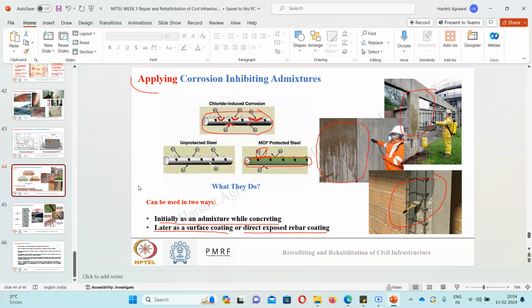So you need to make sure that your outer columns or surfaces are properly waterproofed. Before waterproofing, you can use some migratory inhibitor which can stop the increasing rate of corrosion. It won't regain the property of steel again, but it can stop the steel from corroding further for some time.